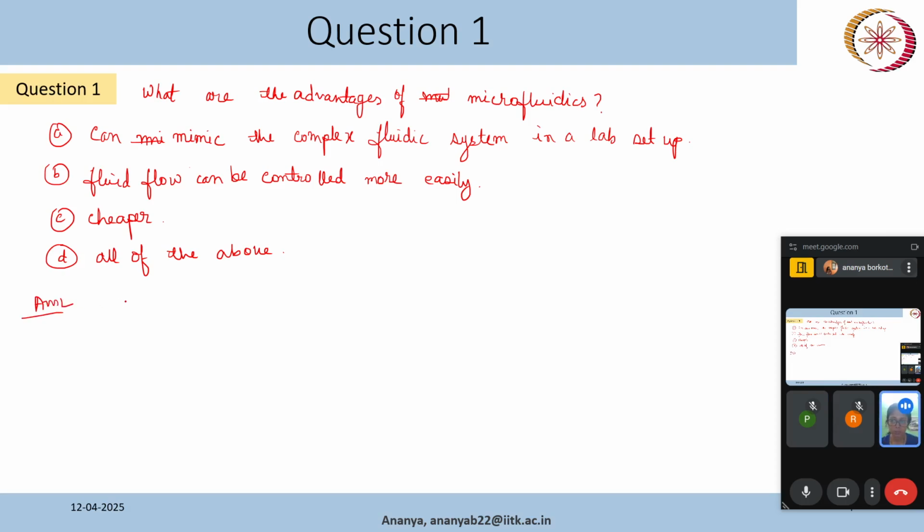We discussed microfluidic systems in this course regularly. Now we know how we can make a microfluidic channel using PDMS and glass. We can make the channels in PDMS using soft lithography, and then bond it to a glass substrate.